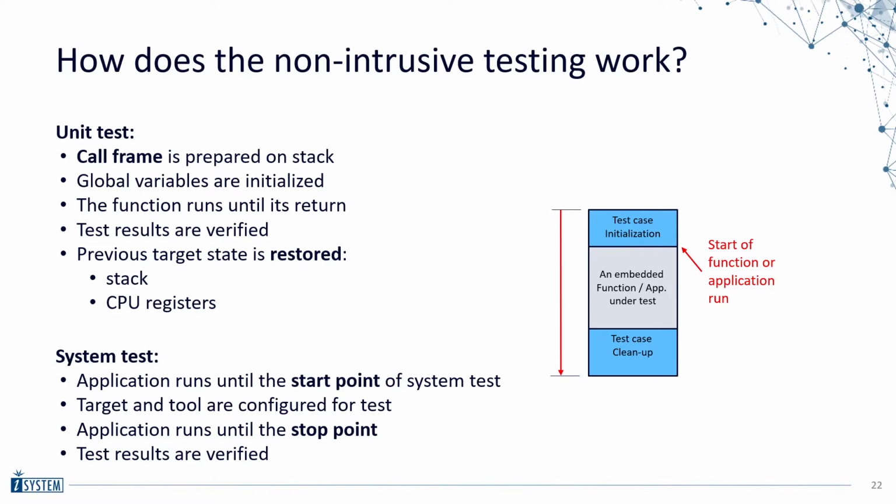When the test completes, testIDEA evaluates return values and other test values against expected results. Execution returns to main, and the next test starts. testIDEA does not restore values of global variables or special function registers automatically. It is the test engineer's responsibility to take care of the initialization of these values before each test.